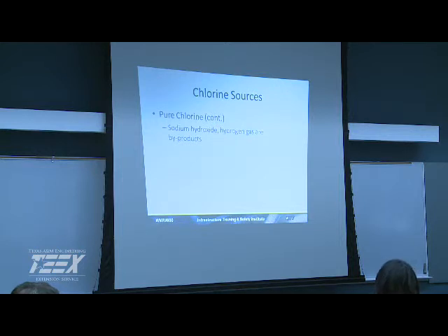And one of the issues with on-site generation, which is a really neat process, is that if you don't have it temperature controlled and it gets too hot in there, you start to produce pure chlorine and hydrogen gas, and it's explosive. We talked about an explosion not too long ago, maybe a year or so ago, over in Middle Tennessee, where a system got too hot, they didn't have it properly ventilated, and with hydrogen gas and an electrical source, they had an explosion and the operator lost his life. So great techniques, but you've got to know your dangers.